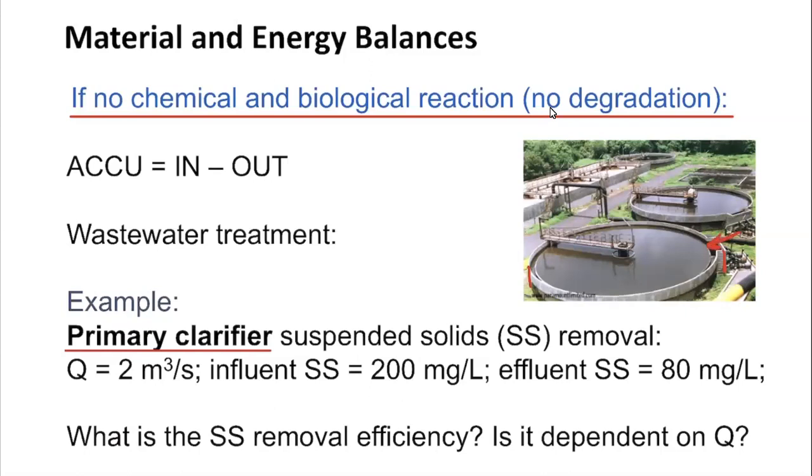The outlet can be at the top or the bottom, while the inlet is at the other. So basically we have this giant reservoir with continuous inflow and outflow of wastewater, and within the process you have gravitational settling of the larger particles down to the base of the primary clarifier.